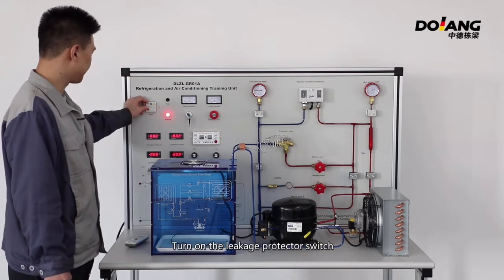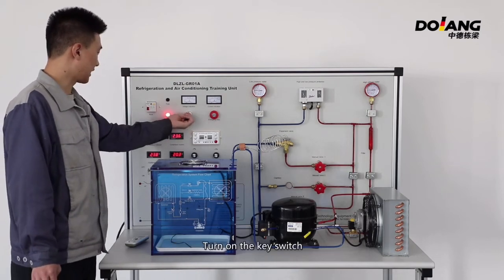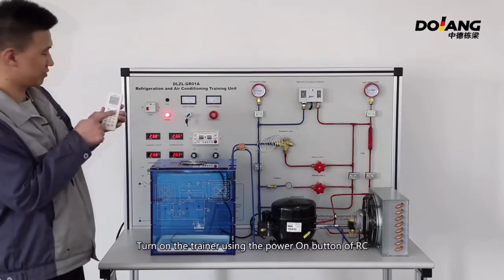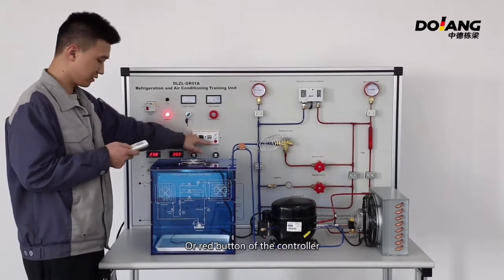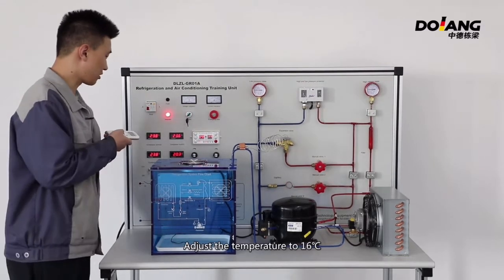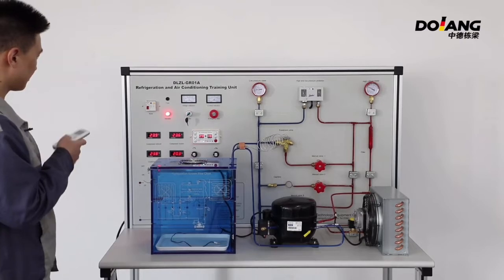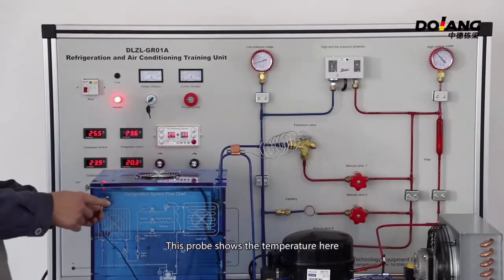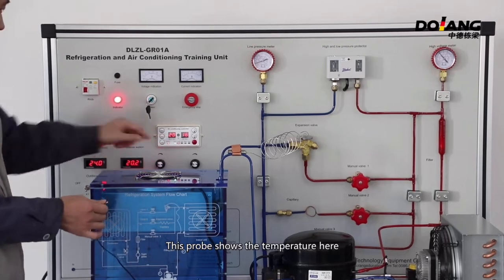Turn on the leakage protector switch. Turn on the key switch. Turn on the device using the power on button of the remote controller, or the red button of the controller. Adjust the temperature to 16 degrees. This probe shows the temperature here. When the set temperature is higher than the measured temperature, the device stops operation.